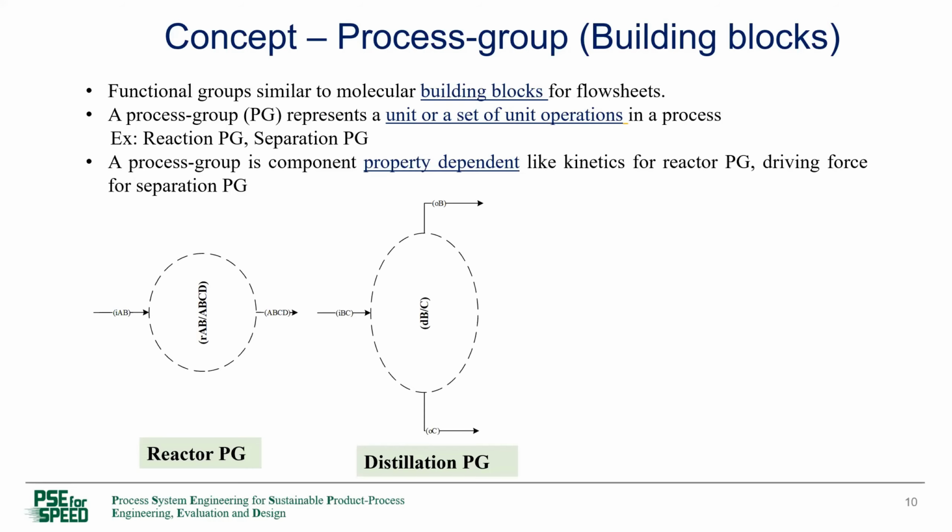So here is a separation. I'm only showing here 2 compounds. So if we have a 2 compound feed, that gives us 2 pure products, B and C. And the rule is that if we have only a single compound in an exit stream, there's nothing more to separate. As long as the stream has more than 1 compound, we need to separate. So then we know where the end point is, and that's why when there is 1 compound, we say that that's the outlet stream. We cannot do any more processing on that.